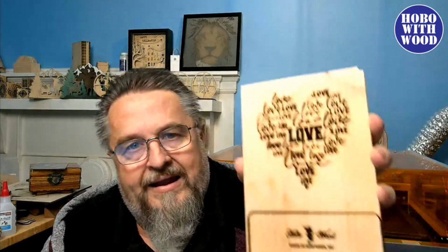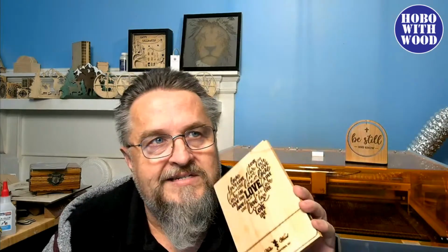Squirrel tangent. A lot of people ask, how do I get a really dark black engraving? Slow your laser down, and reduce the power. To find what really looked good for this, there was no prep work done to it. There's no borax or any of that stuff, nothing, just slowing it down. This was done on this particular maple, 600 millimeters a minute at 15% power.